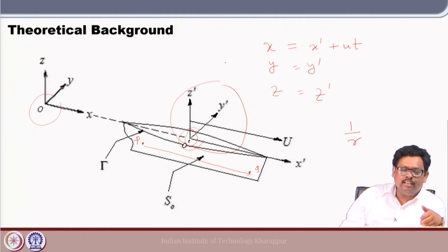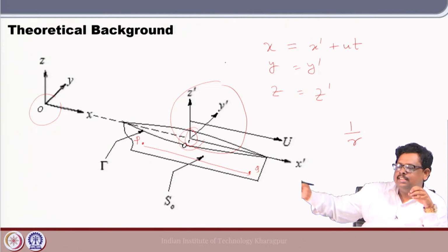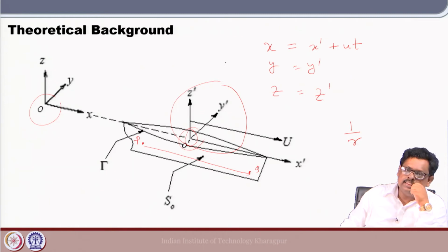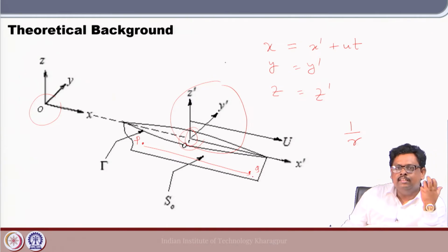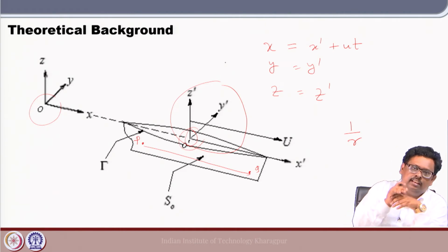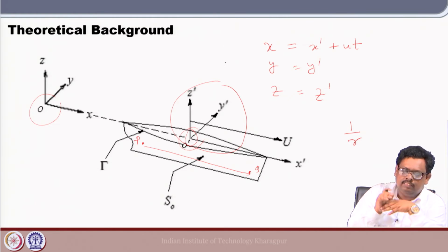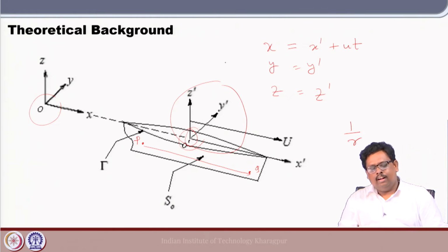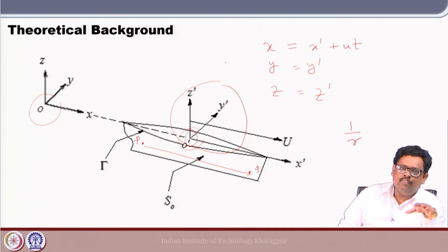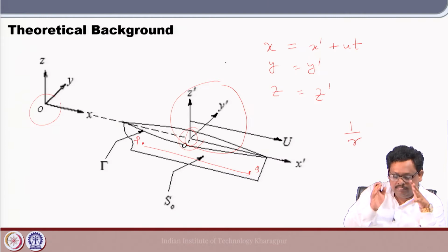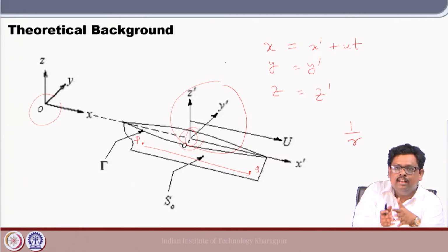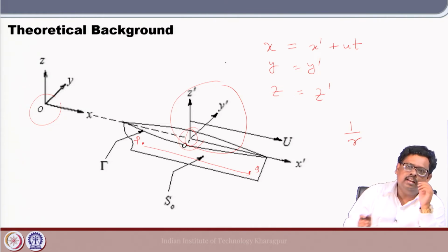However, in the case of an earth fixed system, it is actually translating, right. Therefore, this field point could be any point, so this invariance may not be there. However, in the present situation we have a very stable code for the Green's function evaluation based on the body fixed system. We do the Green's function in the body fixed system, connect the equation of motion, and then the pressure and all we again come back to in the earth fixed system.